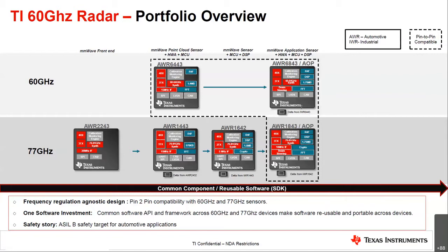This allows you to run all the demos that we provide entirely on the device, providing an edge sensing solution. The advantage of this also, though, is that when we scale down from a 6843 to a 6443 type device, the main difference is the reduction in memory, and then the 6443 device has the DSP. However, a lot of the software investments that are made on one platform can be scaled to the other platform.